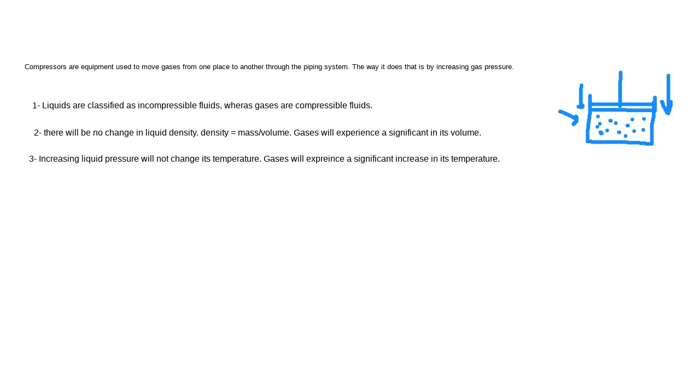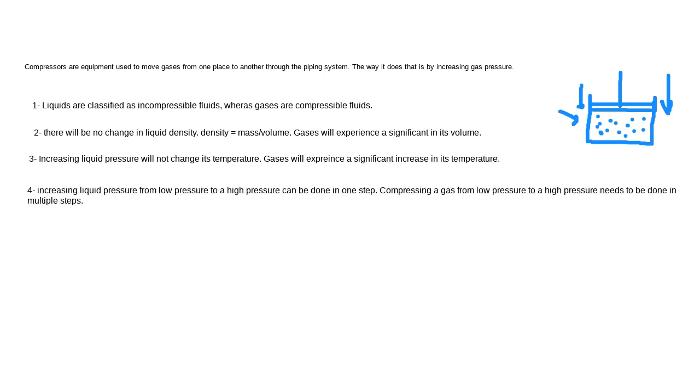Compressing a gas, whereas compressing a gas from low pressure to a high pressure needs to be done in multiple steps. بينما الغاز يا إخوان، إذا عندك مثلا ضغط منخفض جدا مثلا 1 atmosphere and you'd like to compress the gas up to 40 atmosphere, you cannot have like a single compressor, suction and discharge.